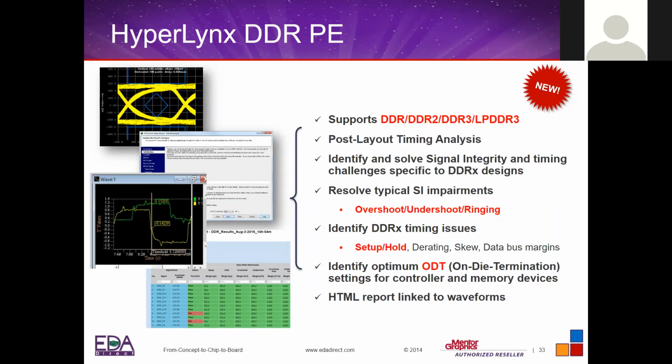So if you don't have this automated checking done on your subsystem, and let's say your subsystem is 32 data lines, 16 address lines, a bunch of control lines, so you're looking at 60, 70, 80 signals to check. If you don't have the automation, you will have to check each signal. You have to measure manually. You have to calculate. You have to bring all these JEDEC limits out and compare. It's a pain, and that's where automation helps you, and a computer can go through these kinds of scenarios very quickly for you. Okay, relieve you from doing all these calculations and just let you focus on the failure. Okay, that's the advantage of automation.